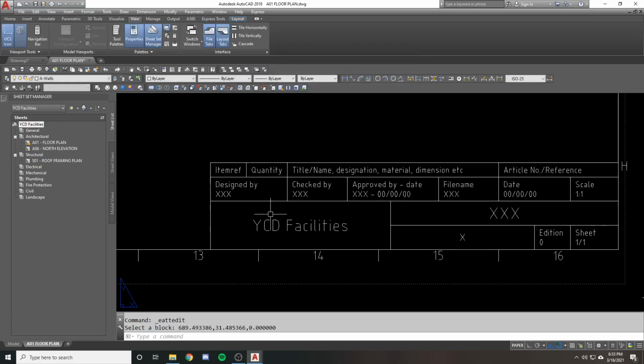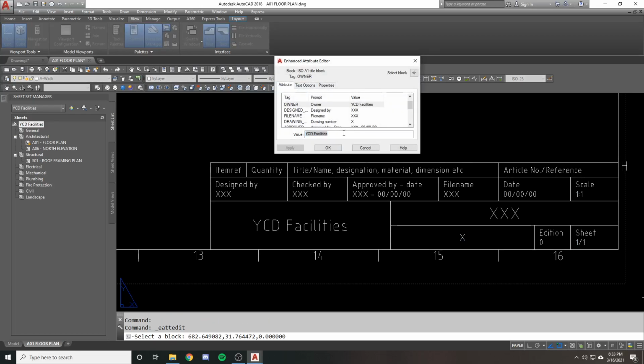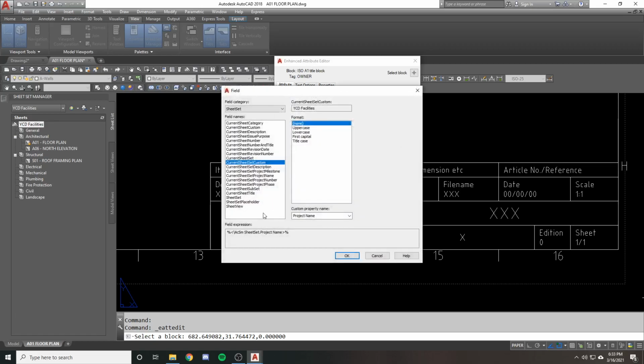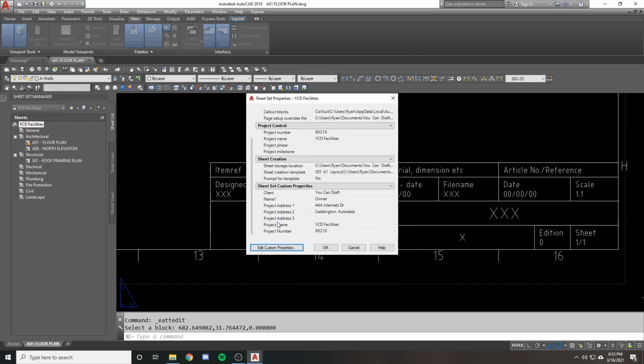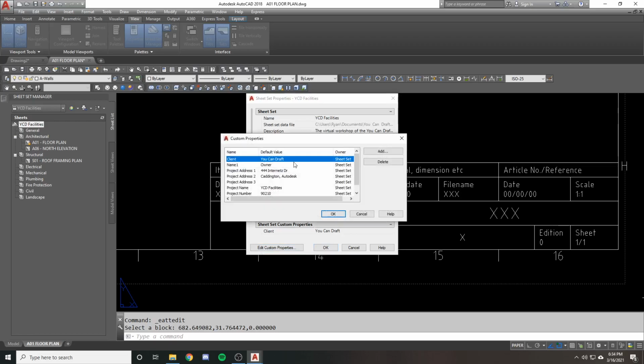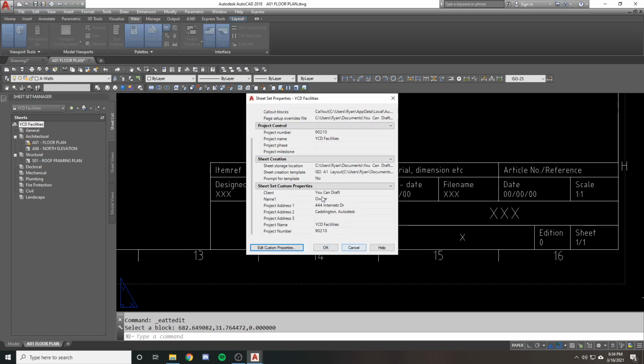Okay, there we go. So you can see, I guess I had to do it from here, not the block. What will happen is this should already be filled in for you. This is a field with preset information. You can see how these custom property names match these custom property names. Now, you shouldn't be able to edit these. You might be able to, but they're under these edit custom properties, and I can get rid of name one now. All of these right here are pre-filled.